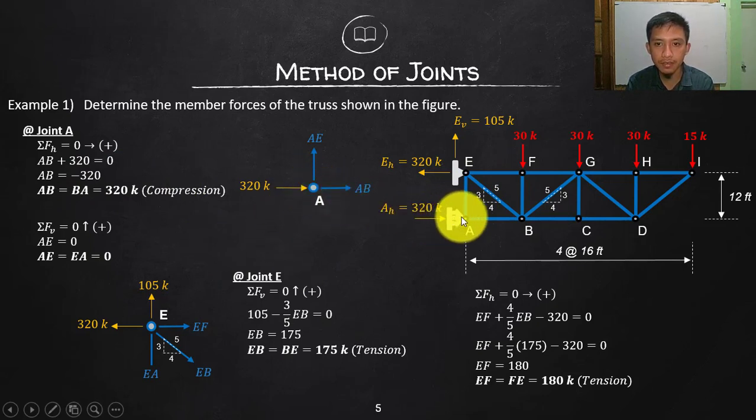At joint A, we have two connected members, but at the same time that is where the reaction, or the support, is located. So there should be the reaction applied within joint A. If I isolate that one, the reaction is going towards the joint, so it means compression. By the way, let's stick to the assumption of assuming a tension always.